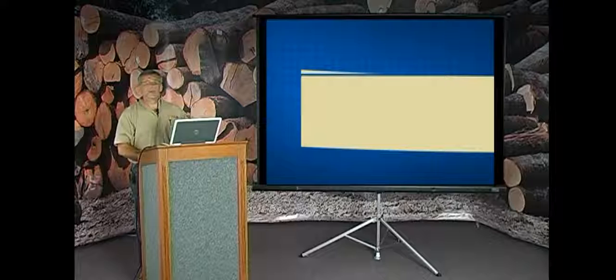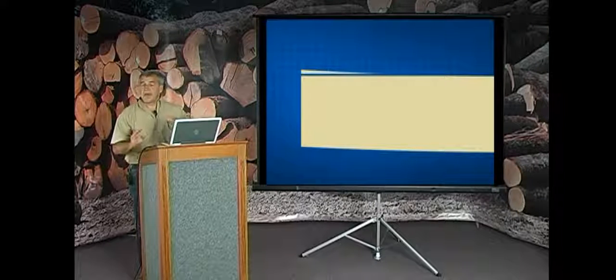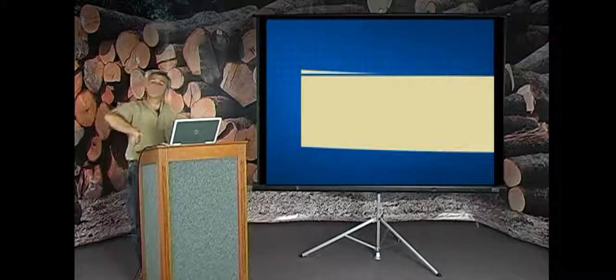If that log has been rolled 180 degrees and you cut right where you cut the last time, you're making a trim cut and you're getting those heavy ends off, and you're watching as that blade goes down through the log to see how much light is under the blade. That'll tell you how thin your middle is. So you've trimmed your heavy ends off, and you don't see hardly any light at all underneath the middle, and you drop down and you make that cut, and that board reacts and the cant reacts, and you may have to roll 180 and make a trim cut again. Yes, it's costing you lumber. You might better have it cost you lumber than a customer.